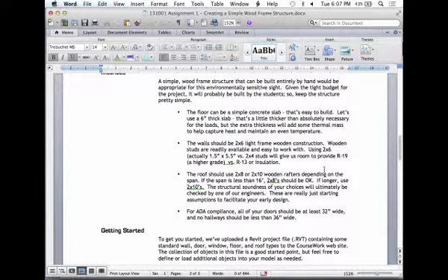There's typically, for something like this, some sort of plywood layer, a sheathing layer that provides some lateral resistance. So if there's an earthquake or just wind, it keeps it from racking. If I have a wall that looks like this, I'm going to look at an elevation view. It has the studs, it has all these vertical members. If I apply a lot of force here, what will happen is it'll rack.